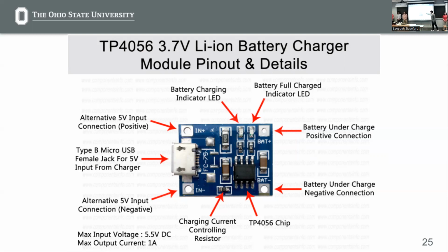And the left LED, when you connect the battery, it will go on, and it's a red LED. And when the battery is fully charged, the bright blue LED will go on. So it's easy to detect the battery charging situation. And another benefit is it can charge the battery and power the system at the same time. So it's good for prototyping, easy to use and really convenient.